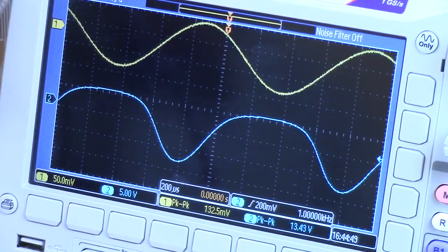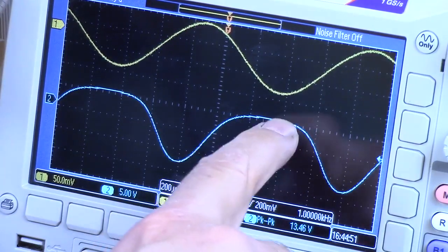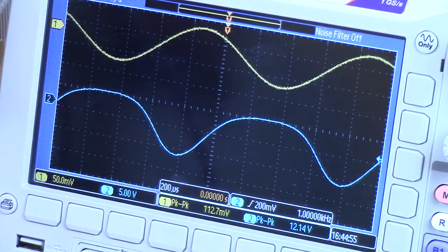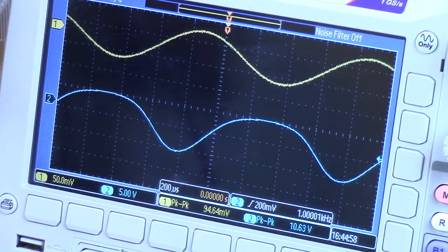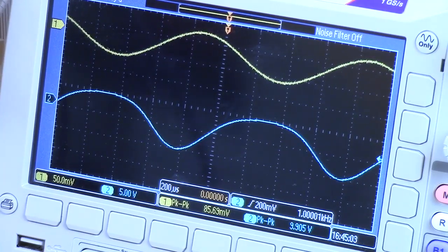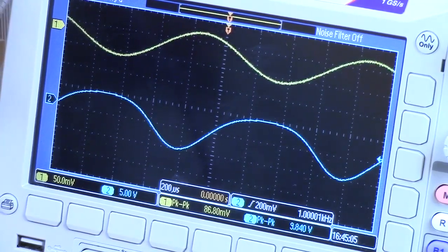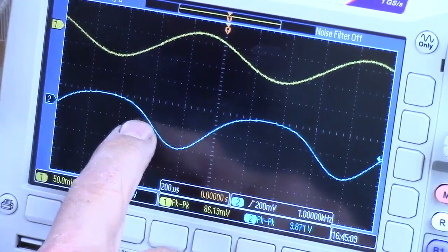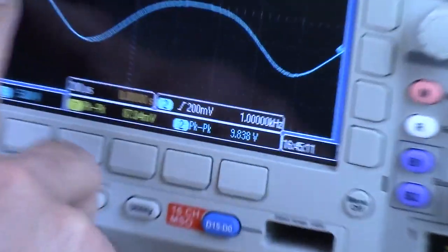But it's pretty fair to say that we have some distortion up here, and where this first starts to come into play is right about there, and this is very subjective. So at this point here, we have a total dynamic range on the output of, if we're on 5 volts per division, about 9.5 to 10 volts.